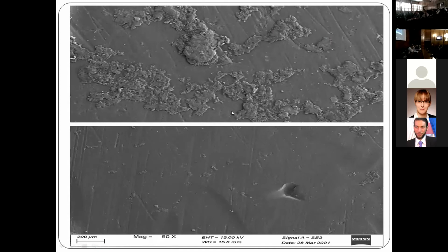As you can see from this image, the first image is for our membranes without any addition of our adsorption material or pre-treatment process. So you can see the accumulation of iron sites and many scales on the surface. But if we use our composite as a pre-treatment process for desalination for any membrane type, nanofiltration or filtration, we found, as you can see, a clear surface. So there is a reduction in the fouling on the surface and a reduction in the chemicals used.